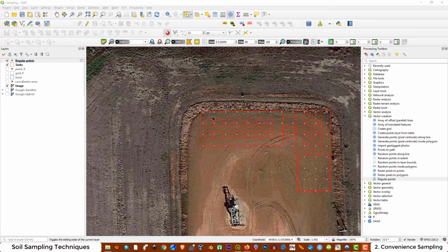Because as you can see, the area is so big, and we could even use a distance longer than 5 meters, but 5 meters is pretty conservative. We have to understand that if there was any spill from the tanks in the past, the contaminant is going to migrate vertically, right? But part of the hydrocarbons is also going to move laterally, though not too much. It depends on what kind of sediments we have at the superficial part of the soils, because that is the part of the area we are going to sample.